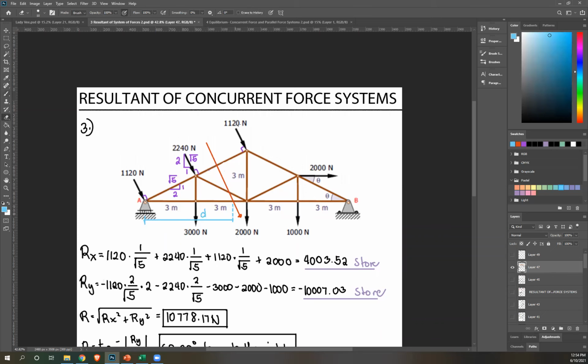Since I need to know D, it's a horizontal distance. If we just solve for RD, the D that we'll get is this, right? Perpendicular distance from our reference point. That is not what I want. I want where it intersects at A toward AB. That is this distance D from point A. So that's why I need to resolve it into components and place it at this point.